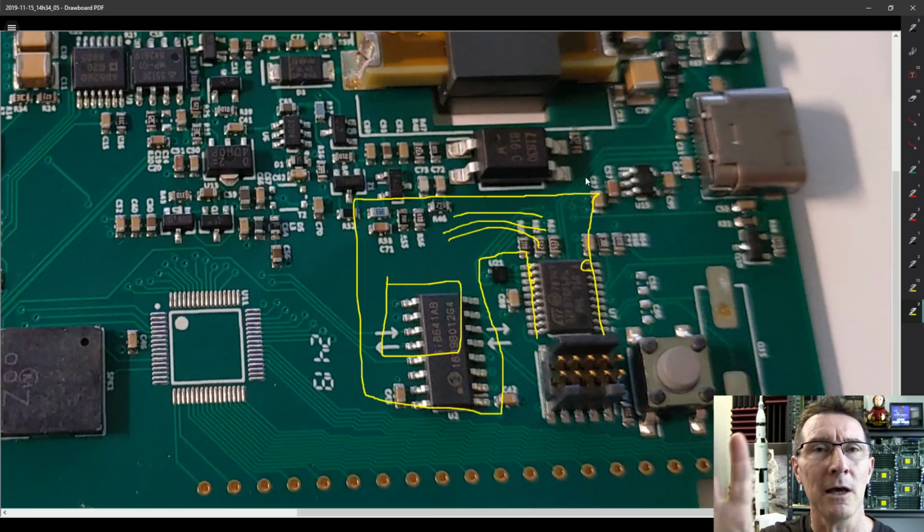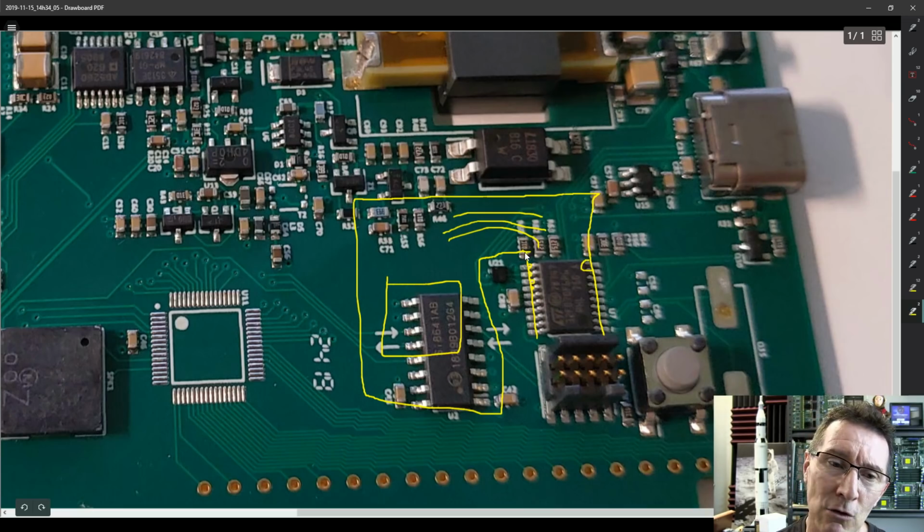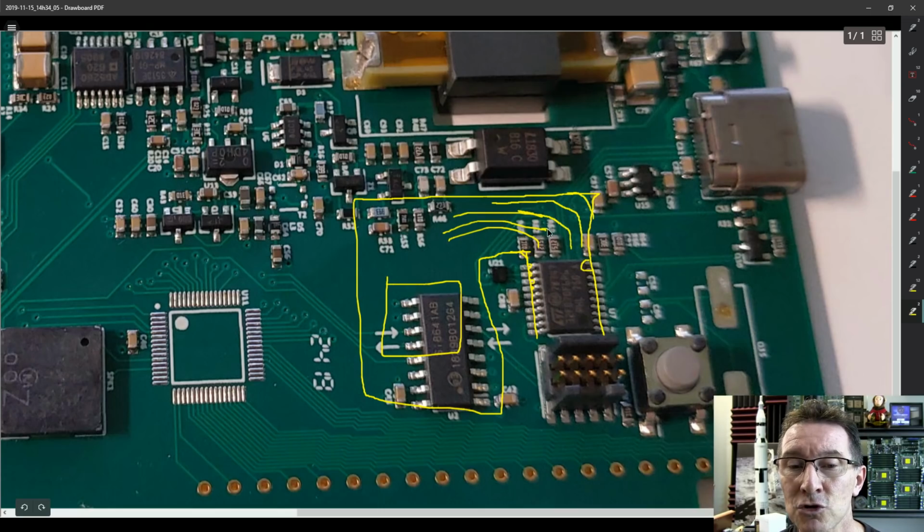This is what I'll go into if I do a specific flex PCB, but I'll just touch on something like this. You wouldn't do right angles like this on a flex. You round everything. On flexes, you round everything, including your traditional right angle traces, like 45-degree traces like that. On flexes, you want to round your traces like that, so when it flexes, there's less mechanical stress on sharp junctions. So you want to radius everything like that, just because it's nice for flex, because they flex, and you don't want sharp corners when things flex. All the mechanical engineers can tell you all about that.